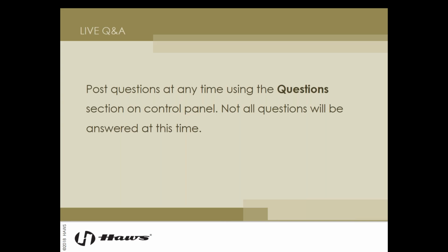Once you're talking about accessibility, you are talking about a high-low feature. You don't have to put them together. You can have a high drinking fountain here and a low drinking fountain some 25 feet, 50 feet away. But the distance away should not be excessive. The disabled person should not have to struggle to travel any further than an able-bodied person to get a drink of water.